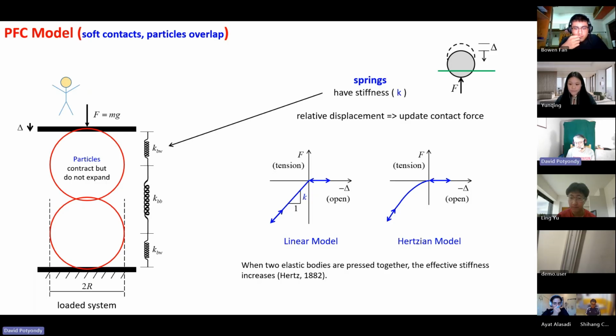Most people doing bonded particle modeling just use the simpler linear spring model. Often people who are doing granular flow, like a big giant silo filled with grain where you want to see it flow out, often use Hertzian models. And that's all I'm going to say about the Hertzian models. But this is pretty interesting.